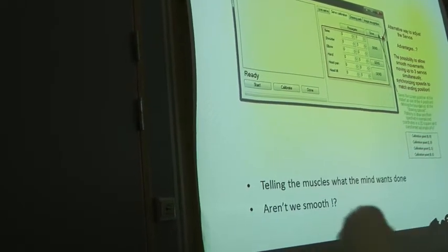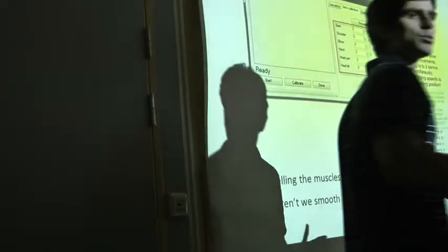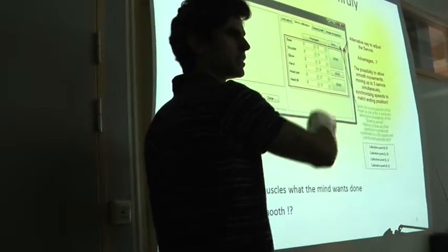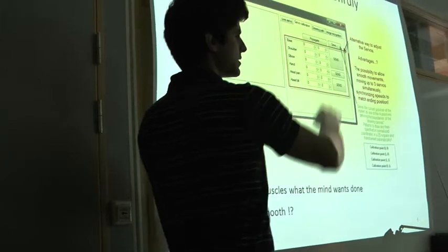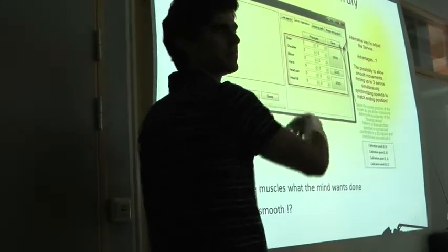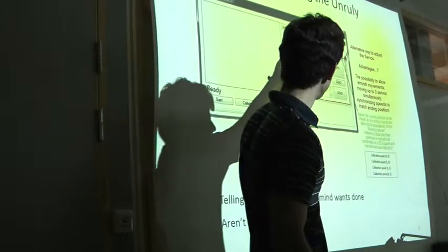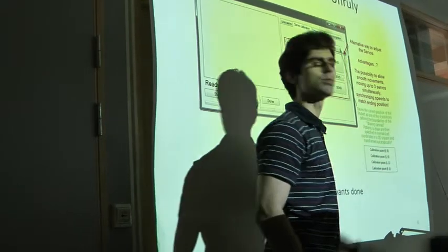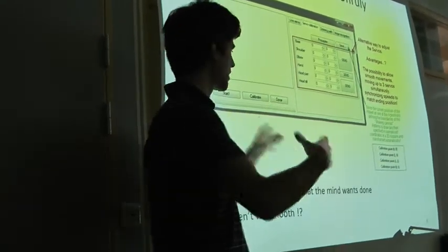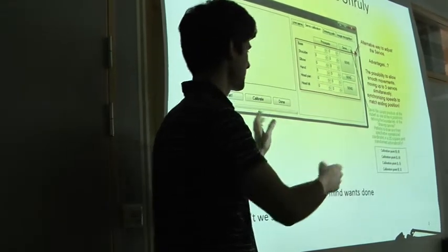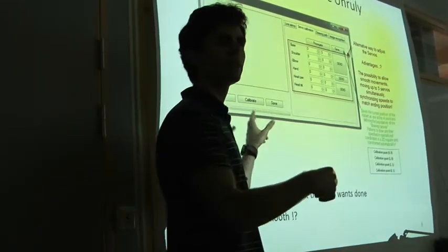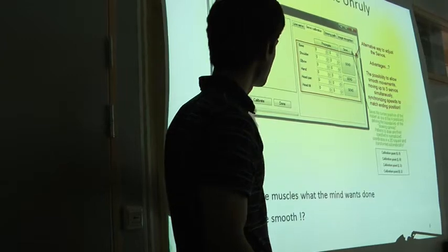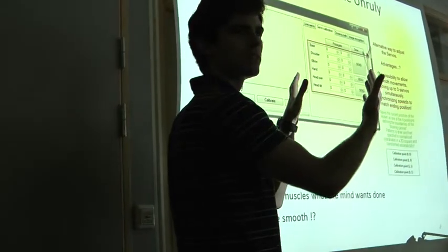And for example, when he needs to draw in a plane, we need to define the 4 points, define the plane at the coordinates with the maximum limits that he will be able to reach. So you can set the point and click save, and the calibration point for 0,0, 1,0, 1,1, and 0,1 of the plane that he's able to reach, and the coordinates from that plane. Then you can specify the coordinates in 2 dimensions in proportion to that plane, which can be in any place in 3D, and these coordinates will be extrapolated to the space of the Hubert in 3D.